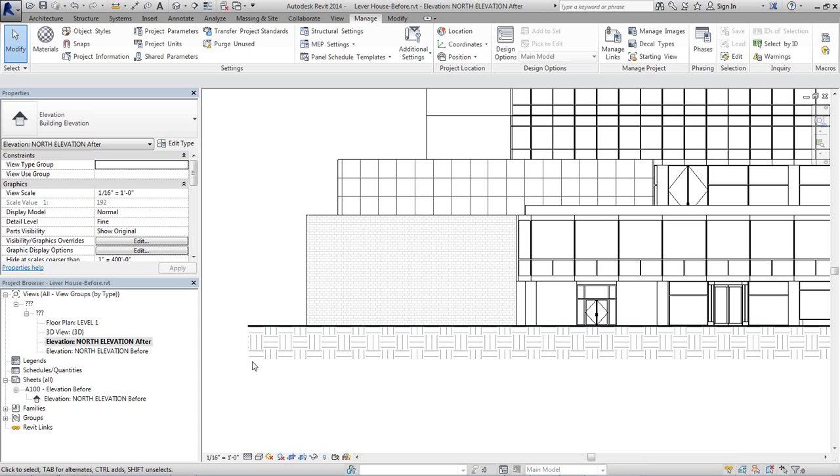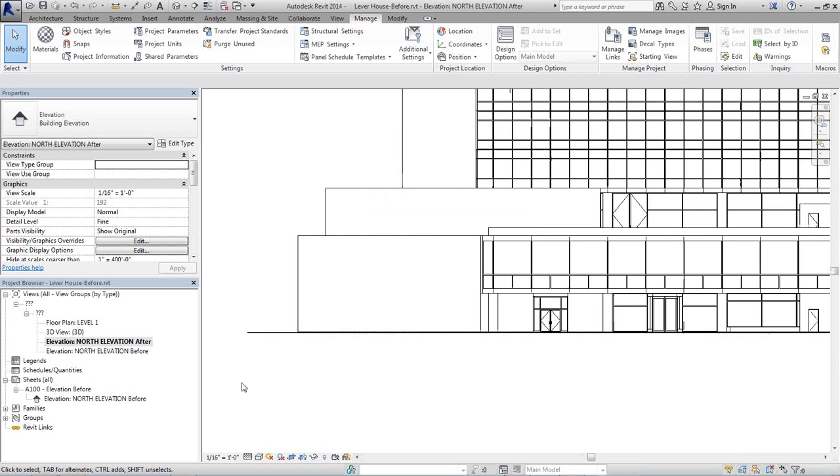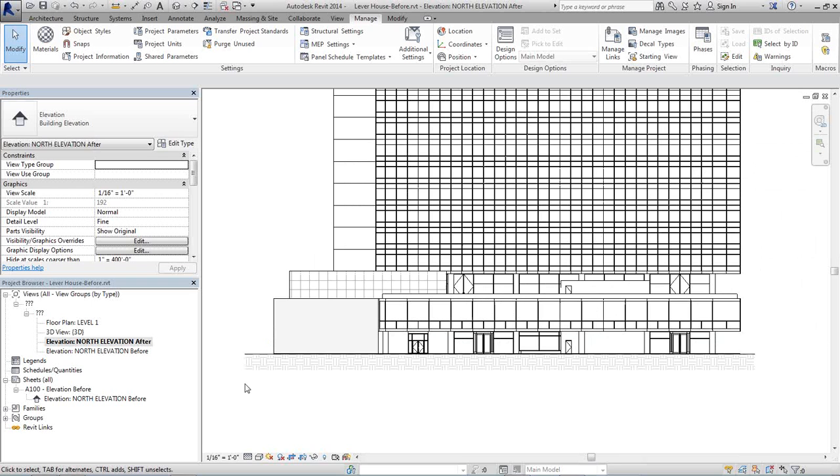But in this elevation that I'm looking at here, let's say I don't really want to see the earth hatch, but instead I just want to see a heavy line running through this thing. I could maybe hide this, but then maybe there are model elements that exist below the site, so I would see a bunch of stuff that I don't want to see. And I could also probably change the material so that I don't see this hatch anymore.